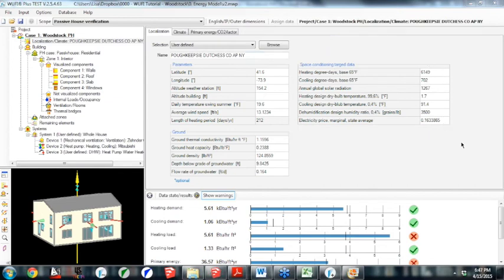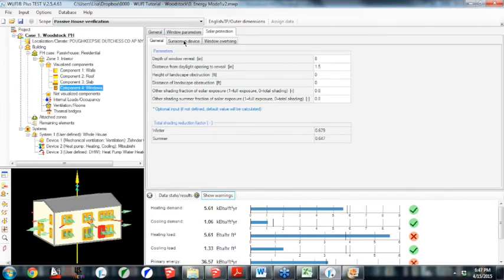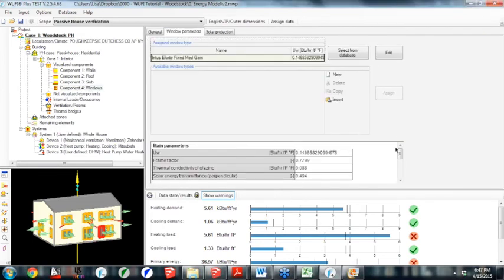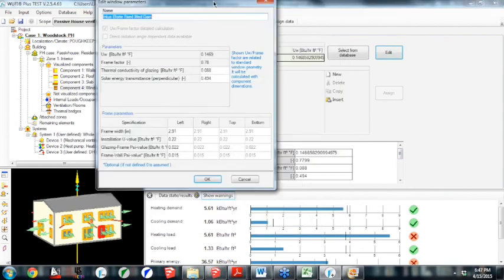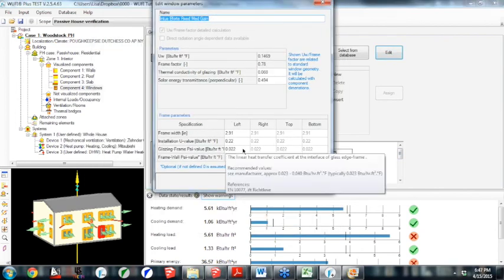So what about framing? I think I might have briefly covered that. Framing in the assemblies. If you aren't entering windows that provide the psi values, the psi spacer, I'll go into it really quickly. It has a very small range. So we'll edit really quick. I'm hovering over the spacer right now. So it's approximately 0.023 to 0.04. I think they've gotten a little bit better, so maybe it's like 0.015 to 0.04, but that's pretty much the range, and it says typically 0.023.